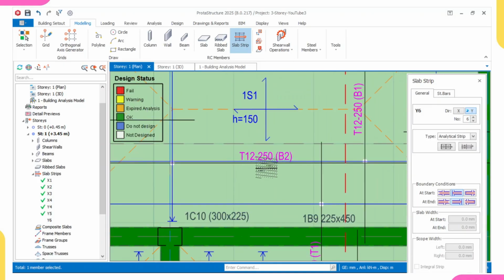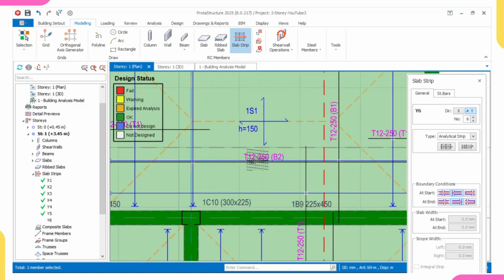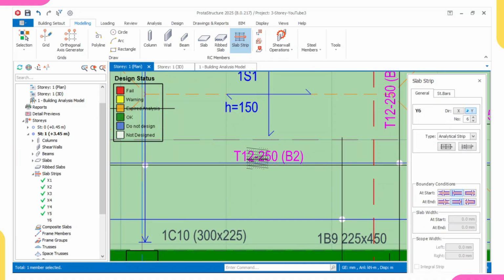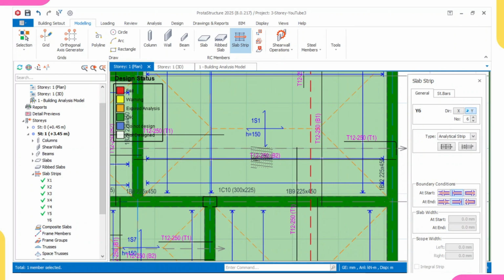And remember, the yield strength that we use is what? 460. So the yield strength at market will be something like 410, 420. It will never be up to 460. So to counter all these losses, I will decrease the spacing, because once I decrease the spacing, it means that I've increased the area of T provided. Do you understand? Moving from T12 at 250, I will now do T12 at 200. I've decreased the spacing, meaning that I've increased the area of steel. That means I'll be able to counter those losses.